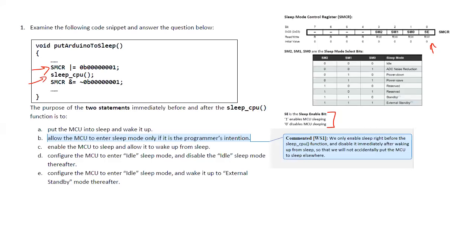If you look back at the data sheet of your microcontroller, you will go into sleep mode in idle state, because the rest of the bits are 0. When you're sleeping, you can wake up in a certain number of ways. All of that is inside the microcontroller data sheet. I won't go through all of it, but you will basically be able to go into sleep mode and then come out of sleep based on certain actions that are performed.